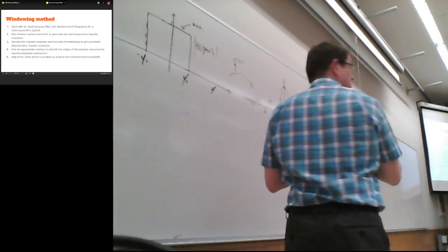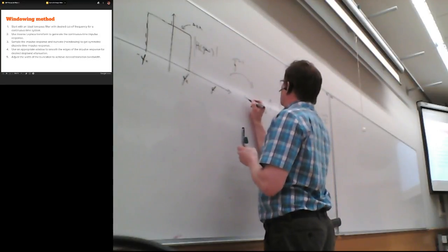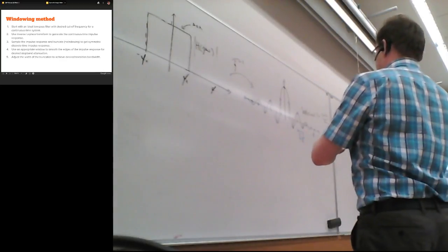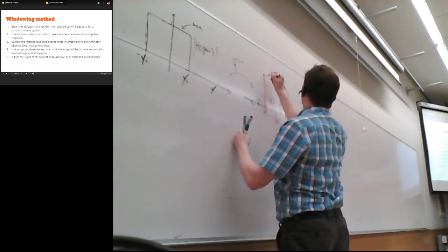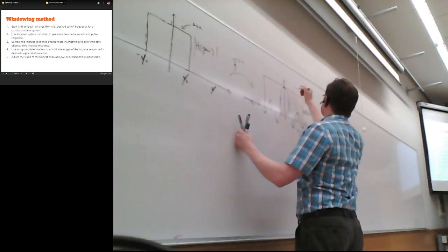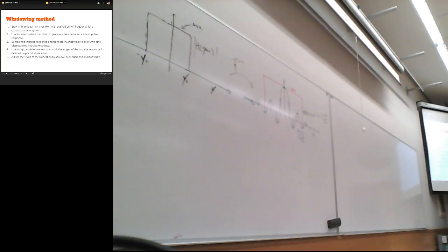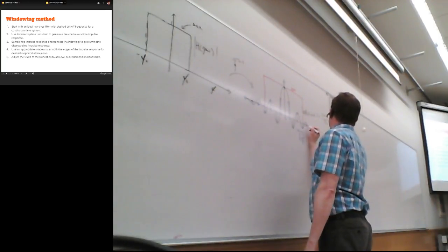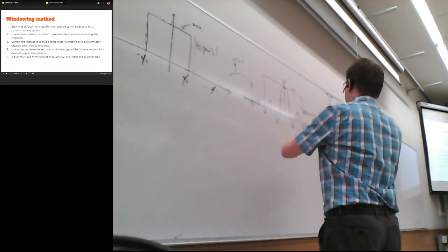So basically you need to cut it somehow, and mathematically this cut means that you will multiply the impulse response with a box. Good. So multiplying with this box will mark this 0, and now we are okay. This is now a finite impulse response system.